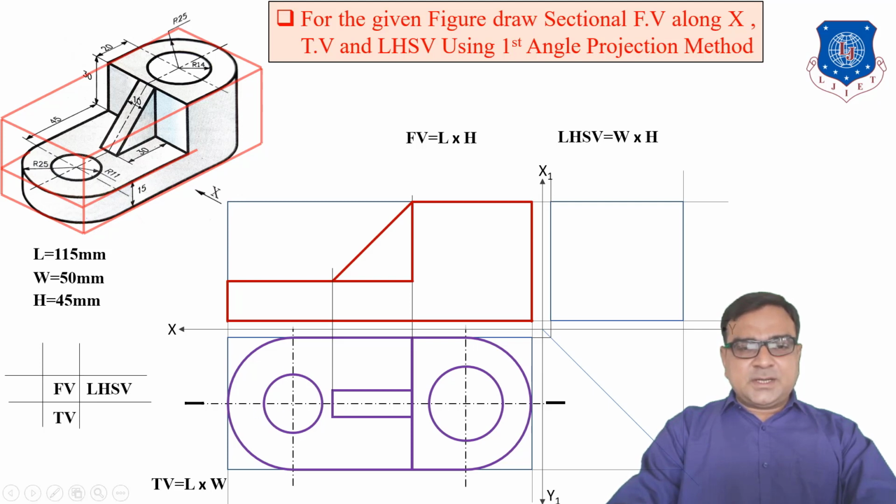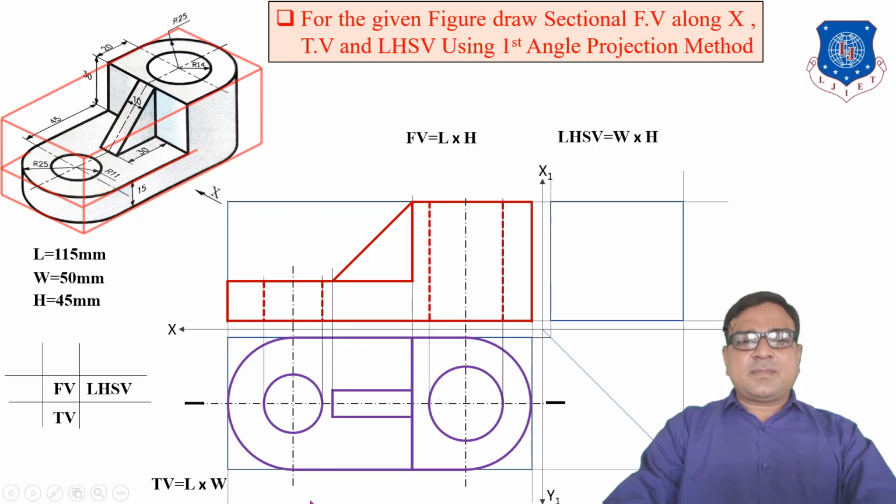Front view of the circle by taking the center line and projection hidden line. So because this is a full front view, this is not a sectional view. From the front you cannot see the hole, so it is represented by hidden lines.